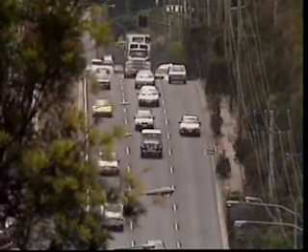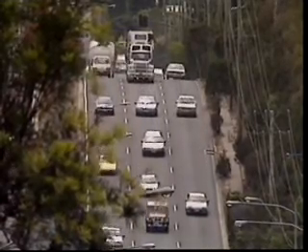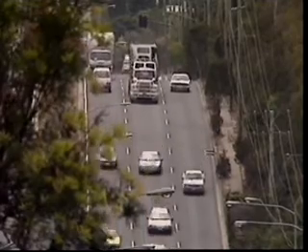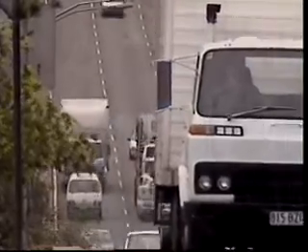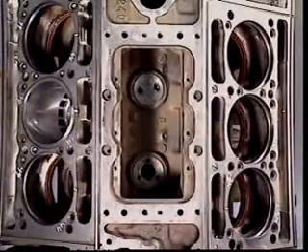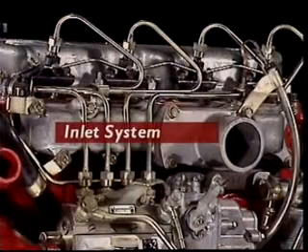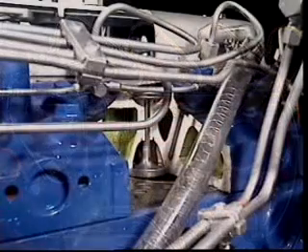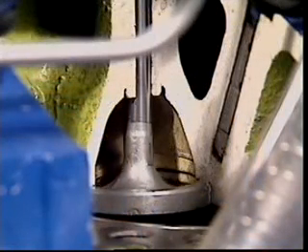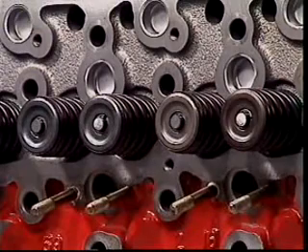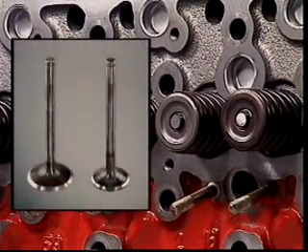Direct injection is usually used for larger diesel engines and two-stroke diesel engines, while indirect injection is usually used for smaller four-stroke diesel engines. The way two-strokes and four-strokes get air is also very different. In a four-stroke diesel, just as in a petrol engine, the inlet and exhaust ports are controlled by valves. But the much higher operating pressures and temperatures in diesel engines put more stress on diesel valves, which are usually larger than those in petrol engines.